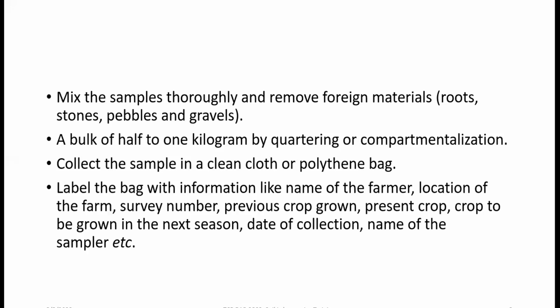For microbial analysis, it should be sterilized and prevented from contamination. For soil moisture, it should be proof against water evaporation. So you can use a closed container, not the normal polyethylene bag, because when you use a polyethylene bag, you are not going to determine the moisture content in the right way, even with a closed polyethylene bag.